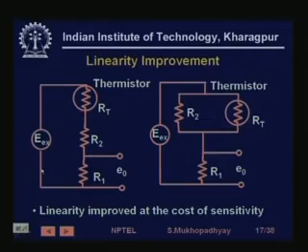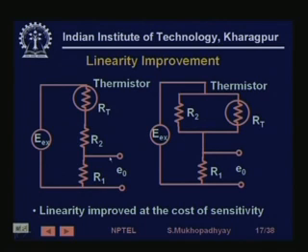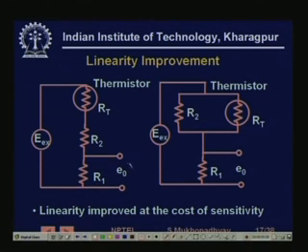You can actually connect certain amounts of resistances in circuits like this, which are called linearizing circuits, and then tune these R1 R2 values such that over a range this combination resistance, that is this E0, is going to be linear with T. So in this equation RT is known, I mean the variation of RT, and R1 and R2 are unknown.